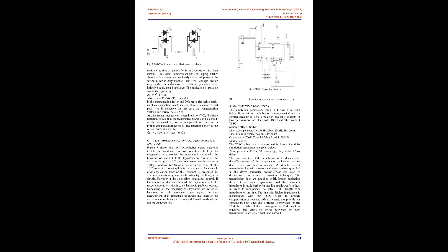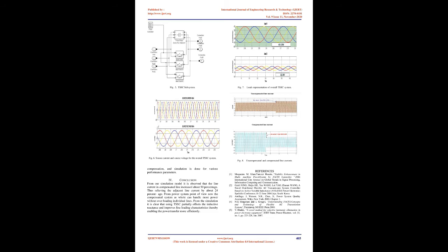The influence of FACTS devices is achieved through switched or controlled shunt compensation, series compensation, or phase shift control. The devices work electrically as fast current, voltage or impedance controllers. The power electronics allow very short reaction times, down to far below 1 second.